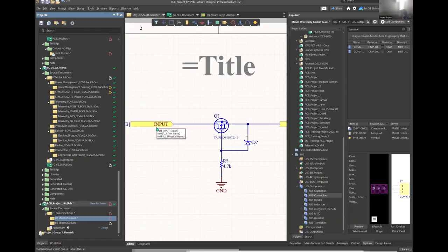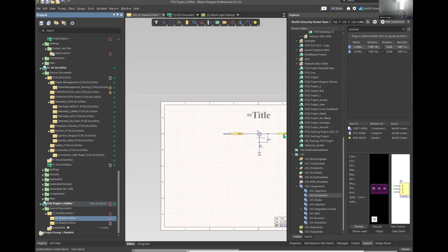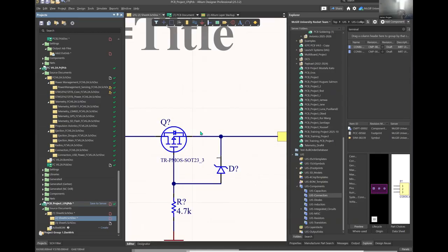Okay, like Altium was like, there's nothing actually coming from the input. Yeah. But that's not quite it because you can see here it never actually gave me a warning for this one because there's two connections on it. But that doesn't mean that there isn't a problem. So that's what I mean, like Altium isn't smart, but it will tell you super obvious things, like there's only 1 pin on this net. That's gonna be an issue like 99% of the time.